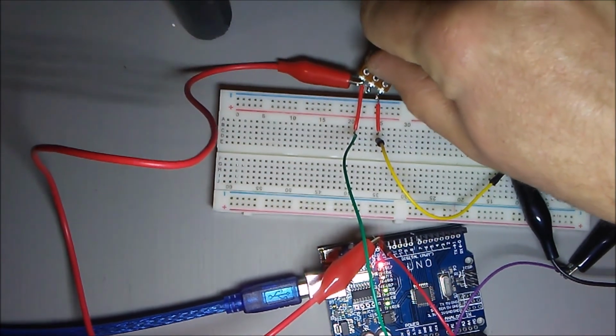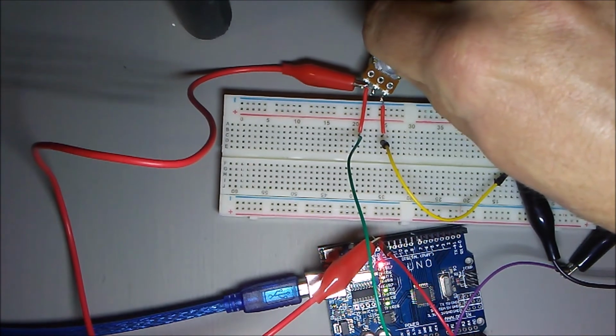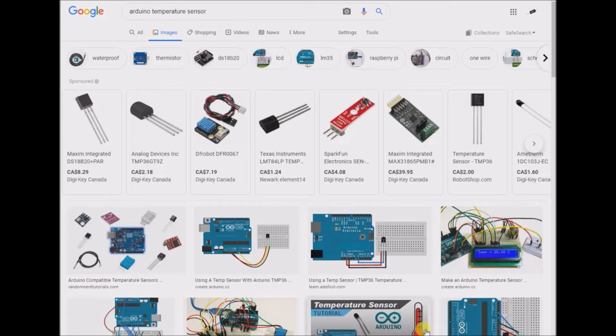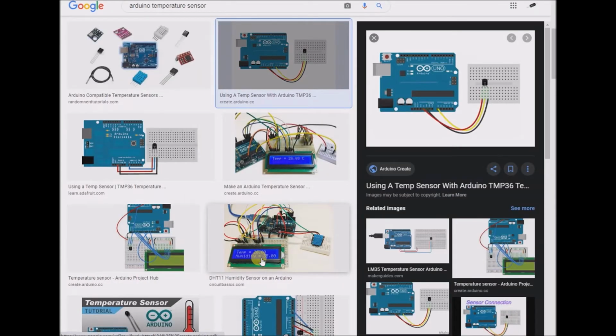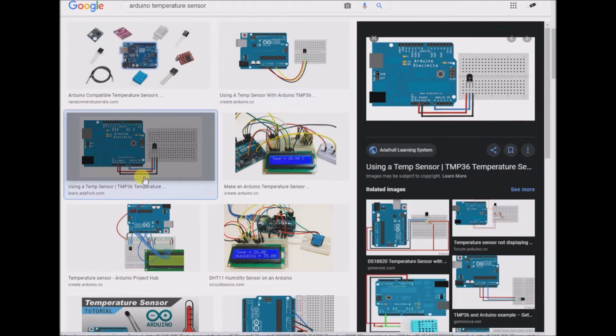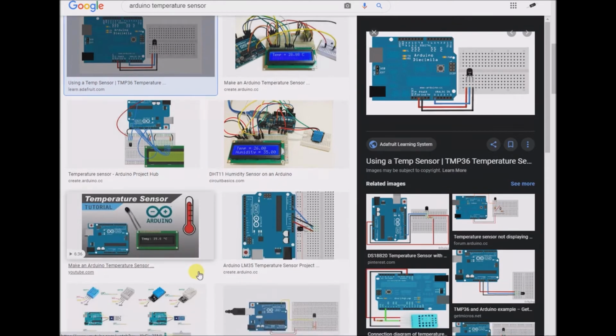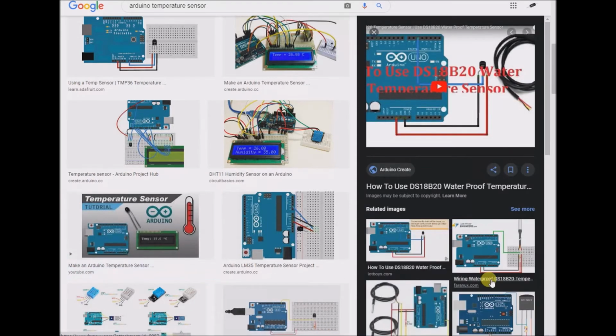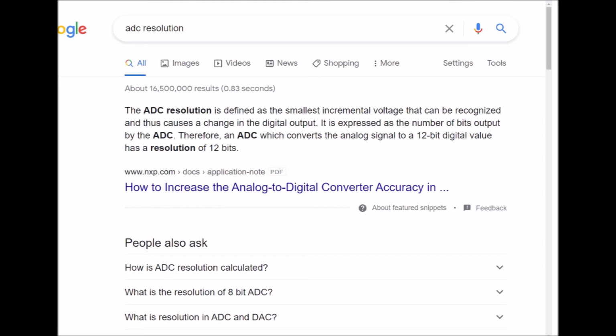The main purpose of the analog pins is to read analog sensors. A temperature sensor is an example. From what I gather, an ADC makes use of power and ground references to create an integer value that represents the analog input voltage.